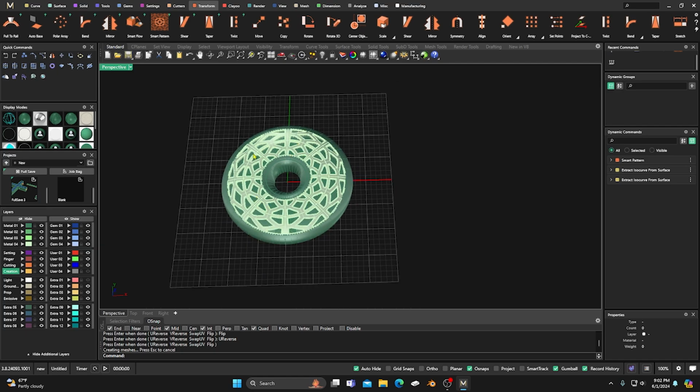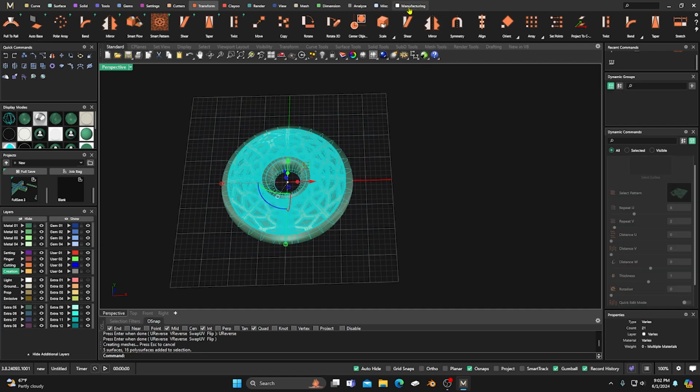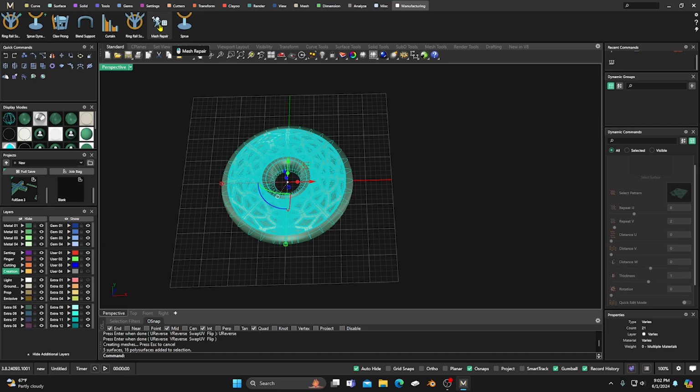So if you wanted this all one color, like all yellow gold, or all red gold, or green gold or white gold, after you put your O-ring on there for your bell, you can go ahead and select it all, go to manufacturing, go to mesh repair, and hit well, it'll just start mesh repairing it, and now's a great time to go hit the snack bar or stretch the legs or get that cup of coffee, right?